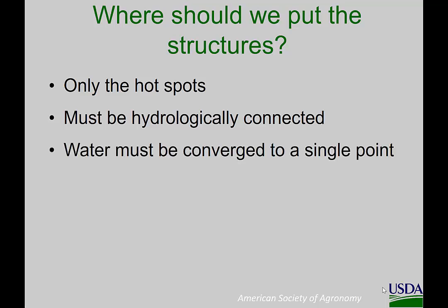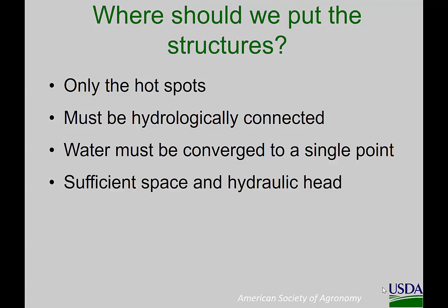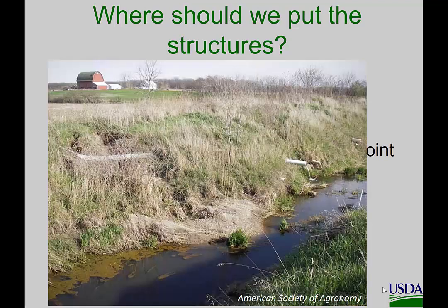You also want to put them in places where water converges to a single point. Remember, you've got to get the water to flow through the media. Water just skimming over the top of a filter media, that's not going to cut it. That doesn't work. You have to force the water through the media. You need a site that has sufficient space and hydraulic head. It takes gravity. These are all gravity driven. So you need hydraulic head to push the water through these at a sufficient rate.